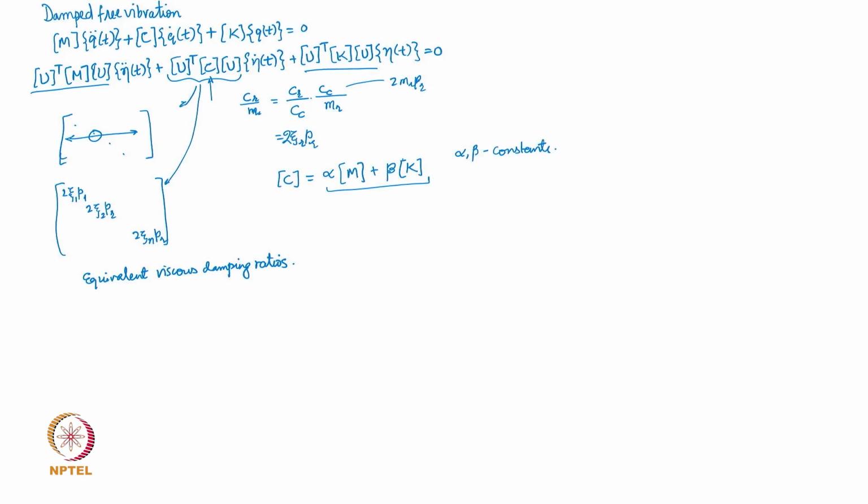Now, this is definitely not going to represent the actual damping in the system. However, it has also been discussed that the actual damping in the system is very complex, and the damping parameters are not so easy to get. So, when you cannot quantify the damping properly in terms of its value as well as its form, for the sake of getting reasonable vibratory solutions, these are the ways of getting around this problem.